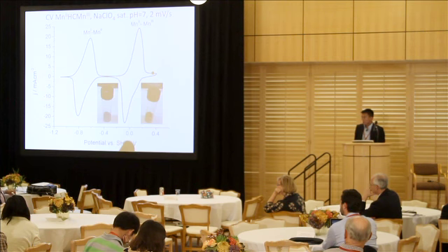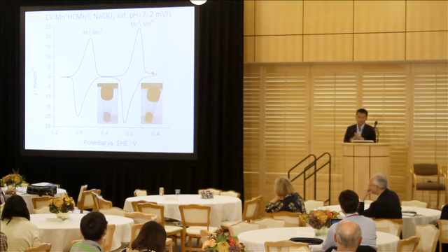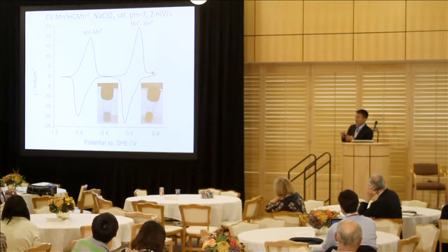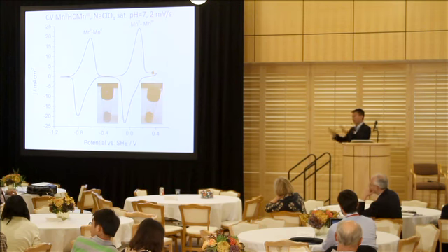Looking at the future, if you had to store gigawatt hours, at what voltage would you store? I mean, would you have a huge number of these devices in series, or would you lower the voltage and store at the volt scale, or how would you do that? So this is 1.2 volt. You would absolutely need multiple of these batteries connected in series as well as in parallel, parallel to build up the current, series to build up the voltage. Certainly, battery management system becomes important later.